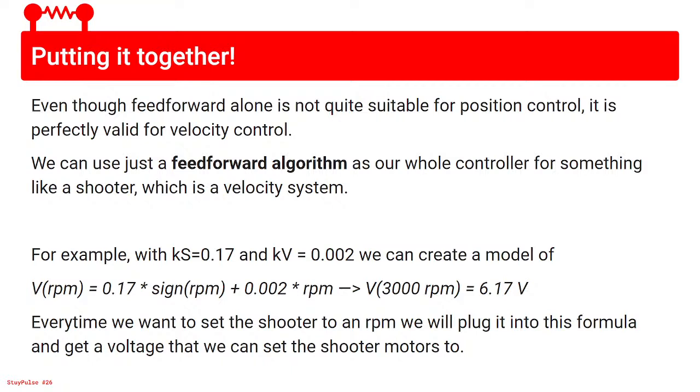There's no acceleration here, because for a shooter we generally just set the target once and don't change it, which means that our target speed is not changing, and therefore there's no acceleration. Because acceleration is your change in velocity over a small change in time.